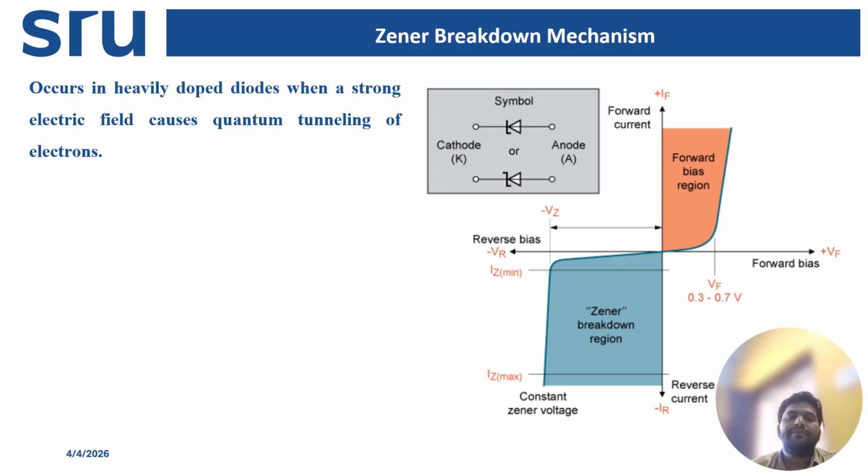What are the important characteristics that occur at low voltage? Very sharp breakdown, and it has a negative temperature coefficient. Current must be limited using a resistor. If current is controlled, the diode will not be damaged in the Zener breakdown mechanism.